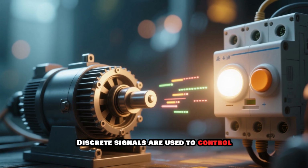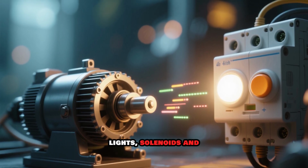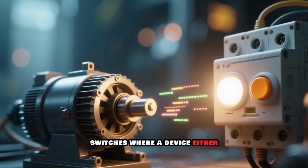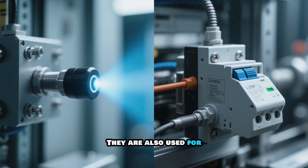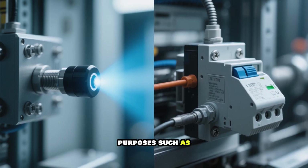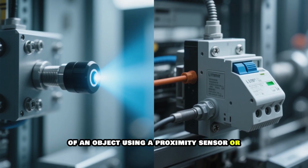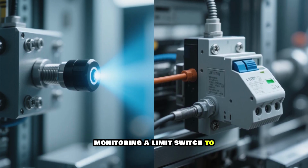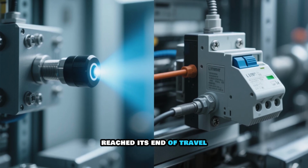Discrete signals are used to control devices such as motors, lights, solenoids and switches, where a device either operates or is inactive. They are also used for sensing and monitoring purposes, such as detecting the presence of an object using a proximity sensor or monitoring a limit switch to determine if a machine has reached its end of travel.